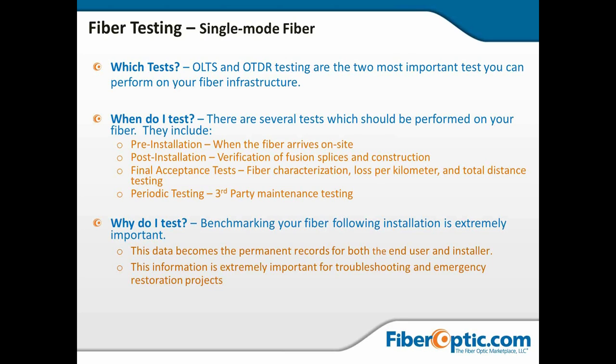Then we might want to do periodic testing just to see if anything has changed out in the field. In Barbados, I found a couple of problems developing where people were messing with the cable. We shared a manhole in several locations with the power company, and the power guys were messing with the cable at a splice location and causing some macro bends, which we found by doing periodic additional testing.